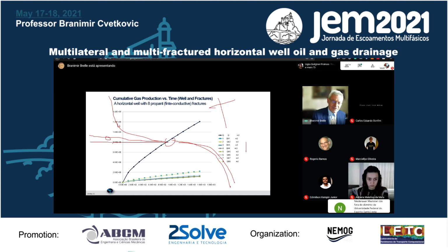Because it is a plane and you are just collecting your flow to the fracture from both sides. Then through the fracture, it goes inside into this. But it is a huge pressure drop here, you see? And that is why you have this. Of course, it will be different if my well is longitudinal, and the fracture is longitudinal.